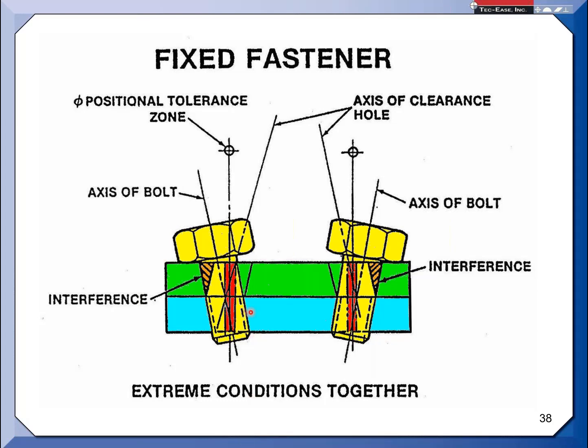So in this case here, everybody sees projected tolerance zones when you're starting to do a concern of the tapped hole depth relative to the thickness of the clearance hole. There's a relationship here. Now those formulas that I showed you, those formulas dealing with either the fixed or floating fastener, they're basing the values on the fact that you are doing projected tolerance zone. So if you use those formulas and do not use the projected tolerance zone, you may be at risk.